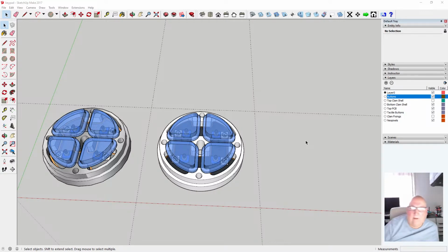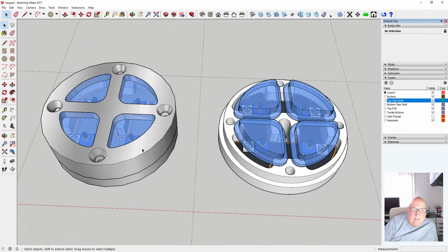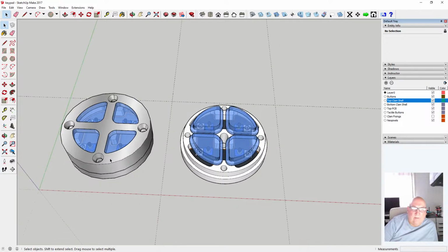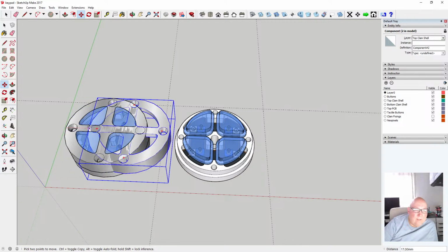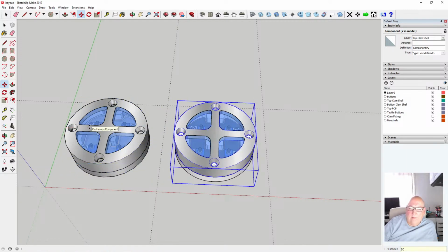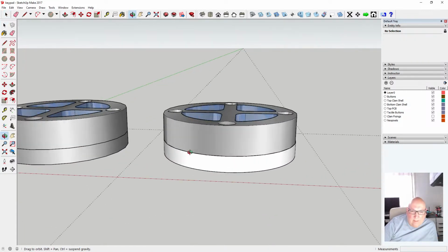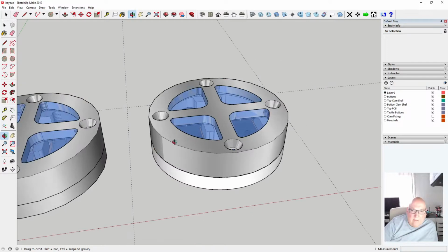Anyway, right, so let's get this top shell. I've only got that one there. So we need to reproduce that, but with a circle instead of this jagged bit. So I suppose we could copy it, paste in place, and move it 80 mil. Okay, so then we're back on there. Got the two together, but we've got a weirdness going on here because we need to convert that outer to a circle.